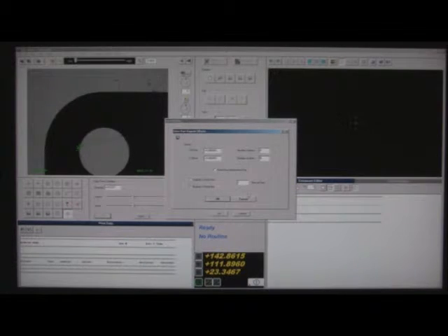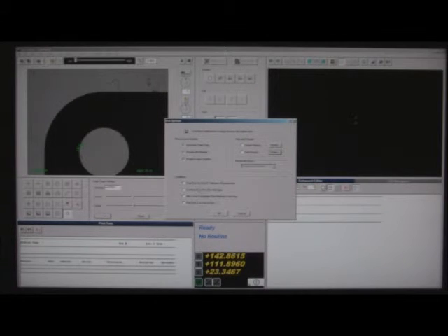Where you might do this is if I had an alignment on a fixture, and then I'm measuring my parts based on that alignment. I wouldn't want to go back and remeasure the alignment each part, but I still want to maintain that in the program. So I may measure it the first time, and then I might start my part program. If the alignment took 10 steps, I would start the part program running at 11 rather than 1. So just a little bit of flexibility.